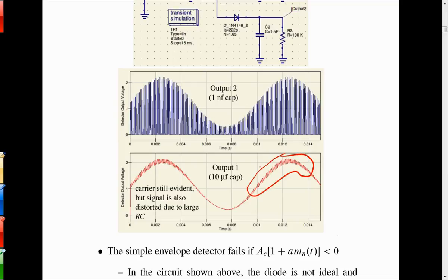If the carrier frequency is high relative to the message, though, then it's not really a problem because it's very easy to have that low-pass filter roll off at that carrier frequency to get rid of all that buzzing and not take any of the message out with it. It's harder in the lab, though, because you don't necessarily have the carrier frequency up that high. So when the two are close to each other, the message and the carrier frequency, then it's harder. You just have to accept some of this buzzing action.